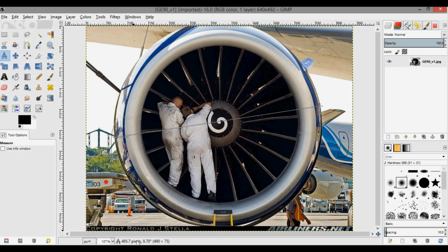So we're going to solve for the D1, the diameter of the inlet, and that's going to be equal to our 156 inches, which is the 13 feet from the maximum, and then we're going to divide by that ratio that we just calculated, which is 1.322. If I do that, 156 divided by that answer, we get the inlet diameter is 118 inches, and that's not very far off from the 115.6, I believe, that we calculated from our calculations from before.